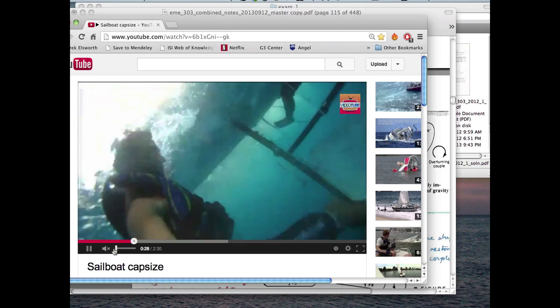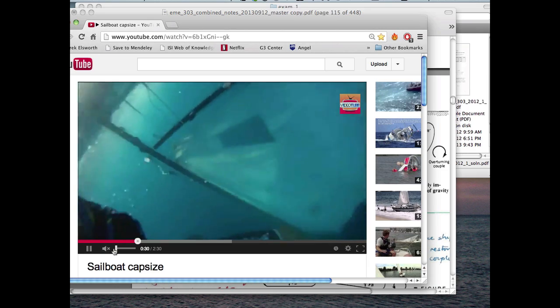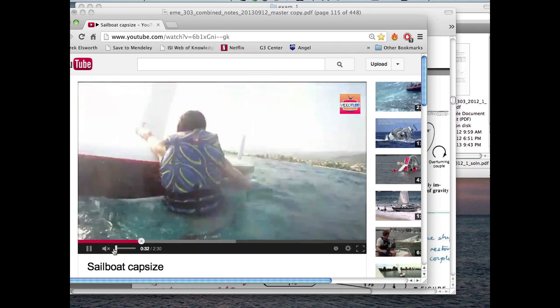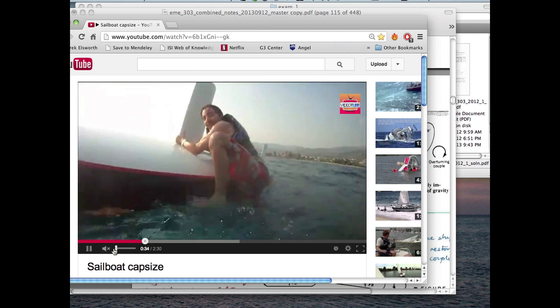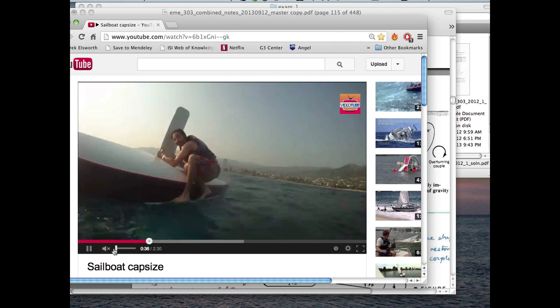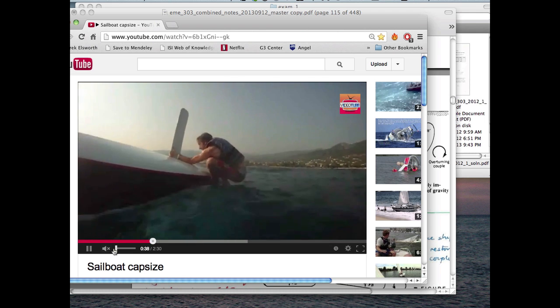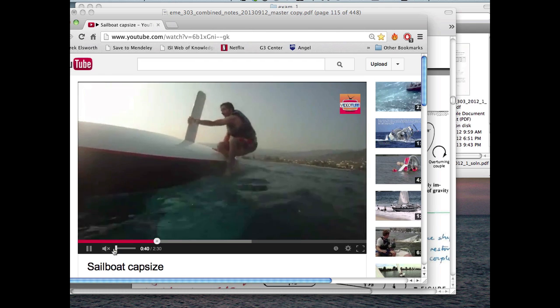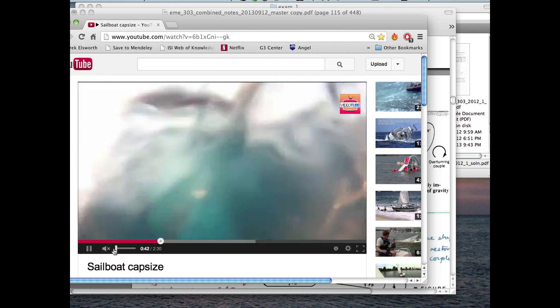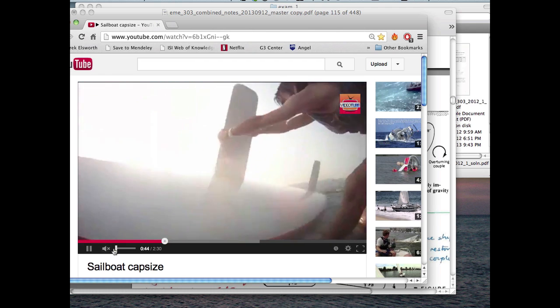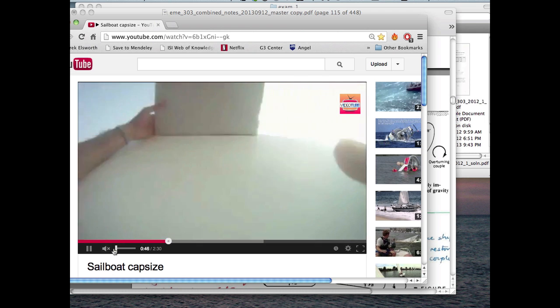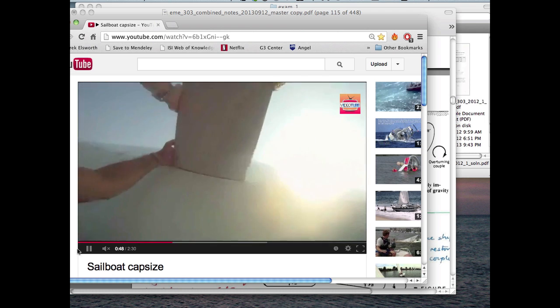And the problems get a bit more difficult when you have things which are only partially submerged, because you have a portion of the structure which is kept outside the water. And of course, the submerged volume changes as you heel over a certain degree, depending on the wind in this particular case. And so the magnitudes of buoyancy in these particular cases change.